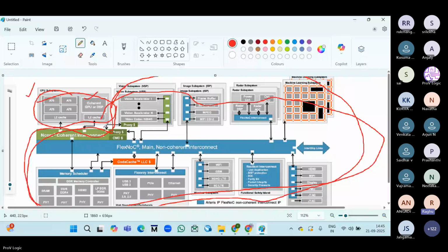Ma'am, here I'm asking, for example, we are taking a motherboard as an example. It has some clock, some reset blocks, and some other blocks. When we come to SOC testing, unit testing is already finished. SOC level testing is all about the integration and how the AXI interconnects and AXI protocols connect each of the blocks, and how the signals are transmitting between the blocks, right?